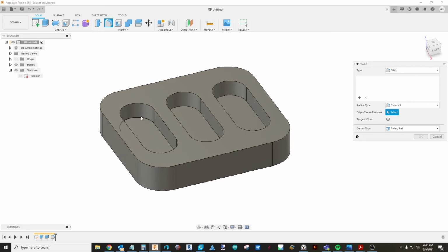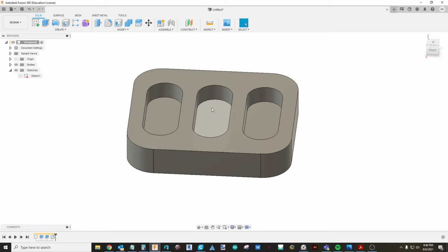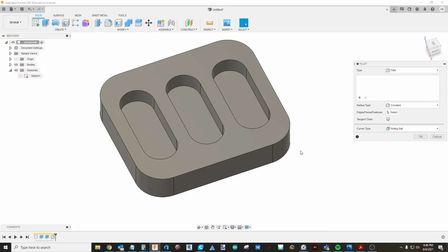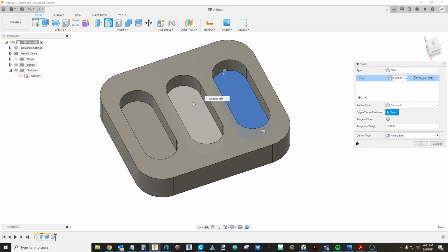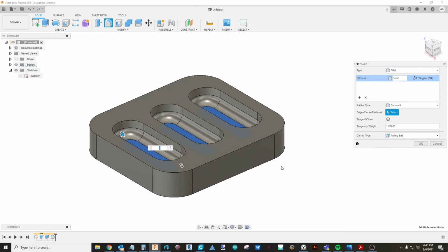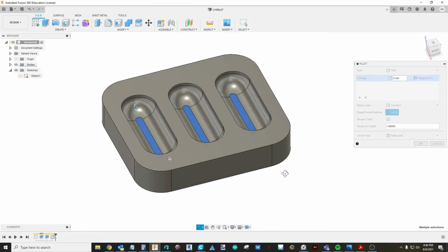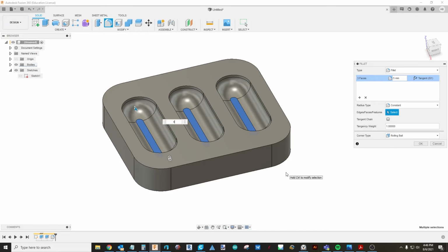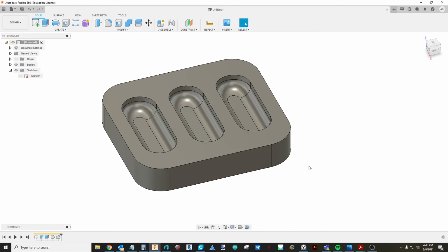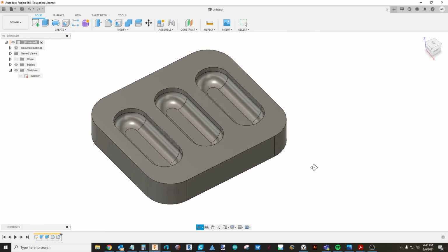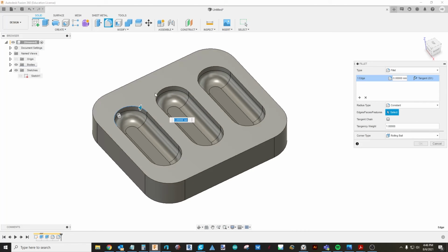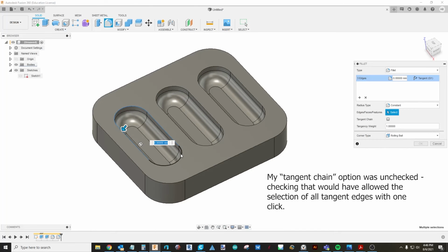And then I also want these bottom face, I want this to be rounded here. So I'm going to click fillet again, select these bottom faces, and put in a number. Let's try 3. So you can see those are now kind of like a curve there. Let's try 5. I'm thinking maybe I like 4. I'm going to hit OK. Now let's also add a little fillet on top here. So I'm going to select a couple of these edges.